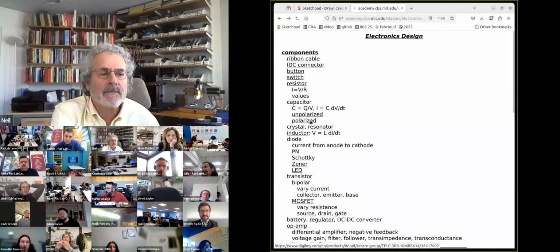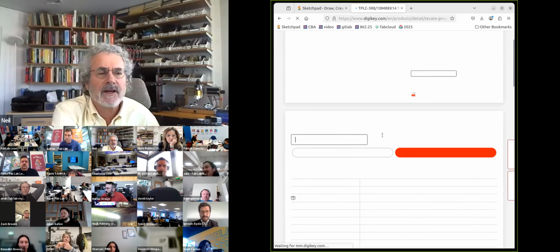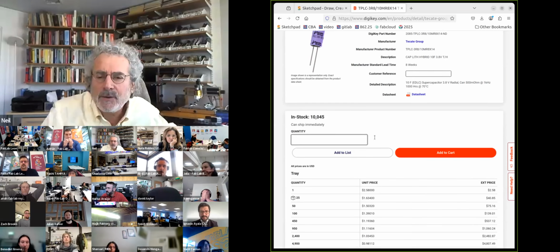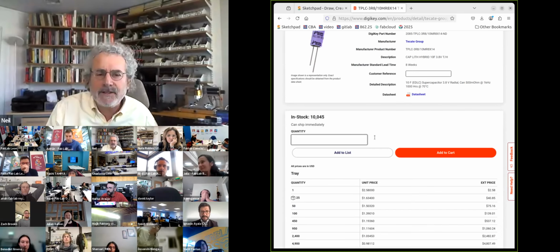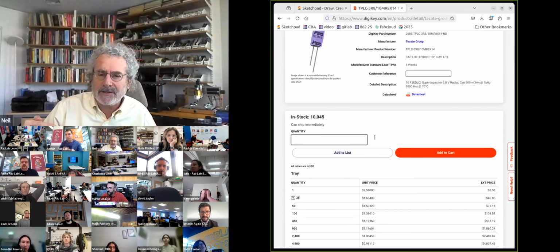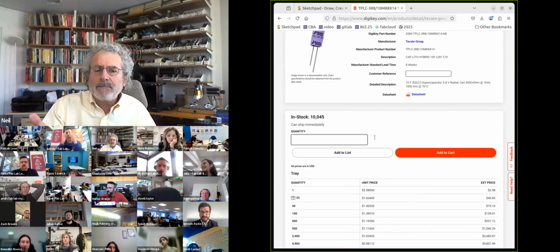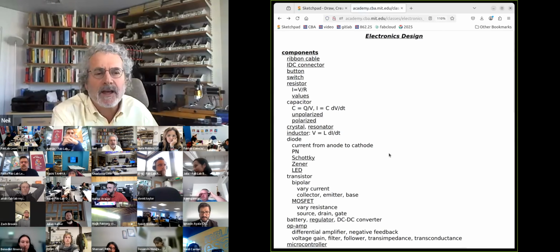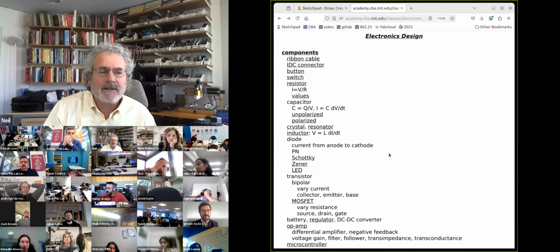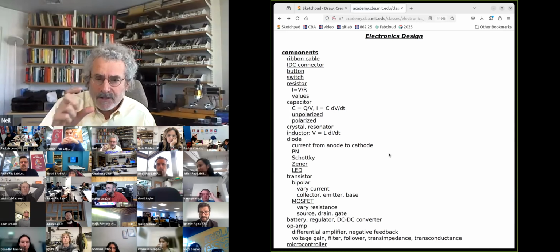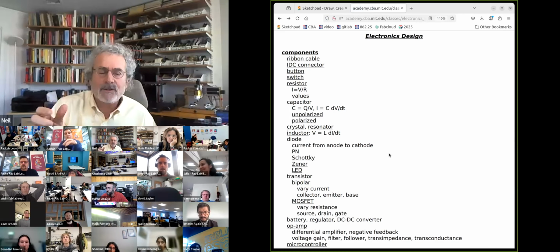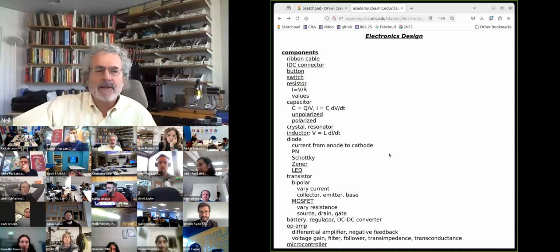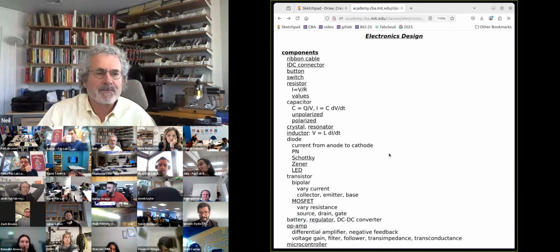And then you can get much larger capacitors. And so this is a supercapacitor. And these we can use to actually store energy. Batteries are more complex to charge and discharge. Capacitors, you just apply a voltage and they charge up. And so you can use a large capacitor as a kind of short-term battery, and you can also use it to filter irregular power sources.